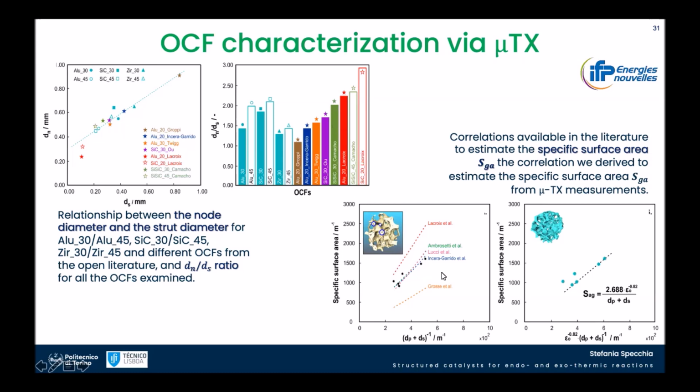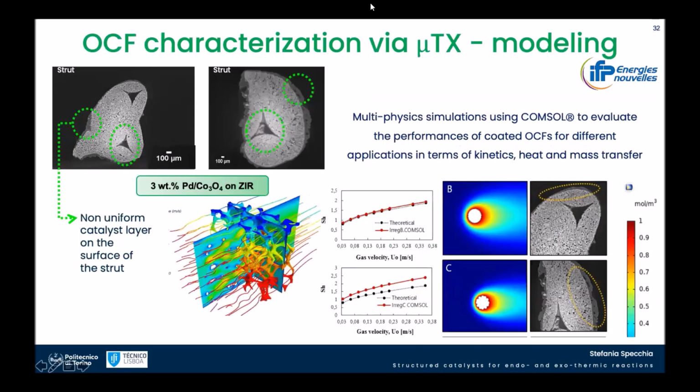And we also found a correlation on how to relate the specific surface area of the foams compared to the literature, which we derived from these kind of micro-CT measurements. Those were very useful also to evaluate the thickness of the catalyst deposited on the foams.